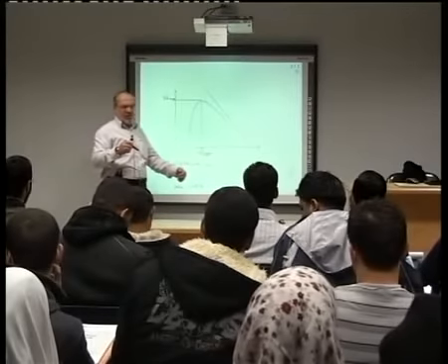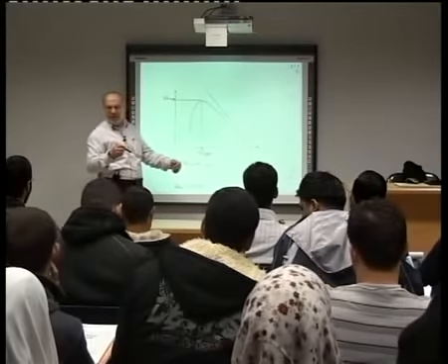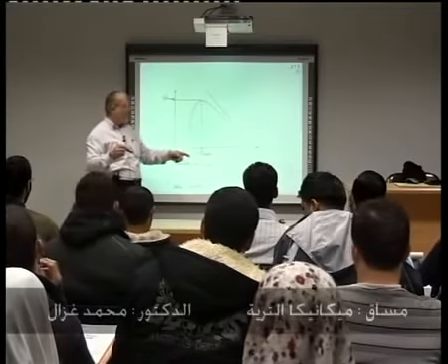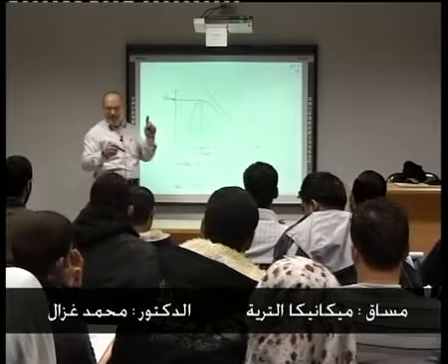So this comes only with one W, with one water content. Any additional water will make the soil weaker. Any less water will make the soil weaker. So we are looking for just one number.